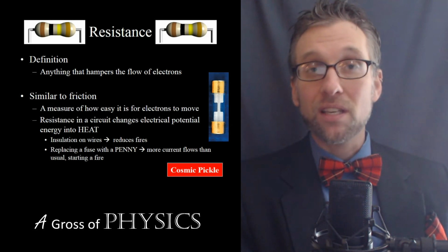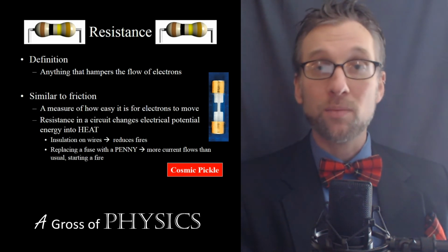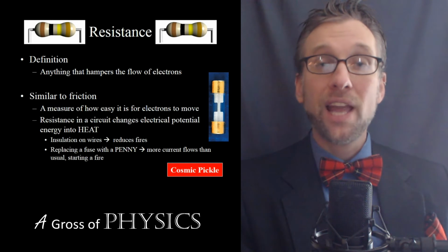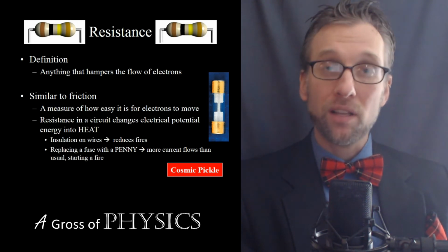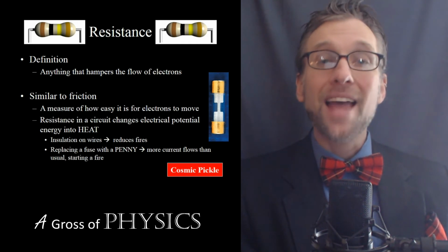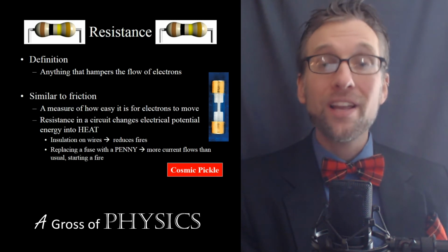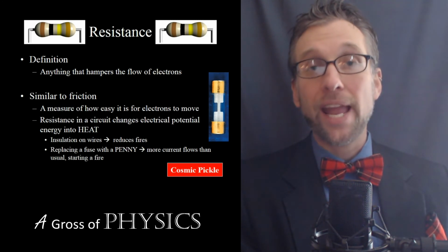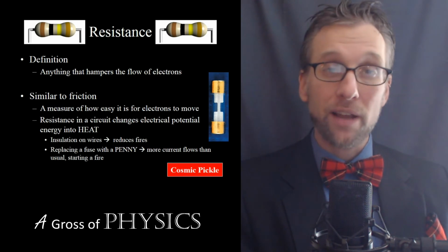Now, as I said previously, a typical electrical circuit in your house is 15 or possibly 20 amps. Now, 15 amp circuits require 14 gauge wire typically. And it depends on the building code of the region that you're living in. But that will ensure, if you follow the proper code, that if you have anything less than 15 amps, it's not going to heat up enough to melt the wires and burn your house down.